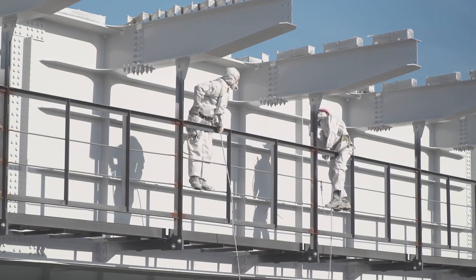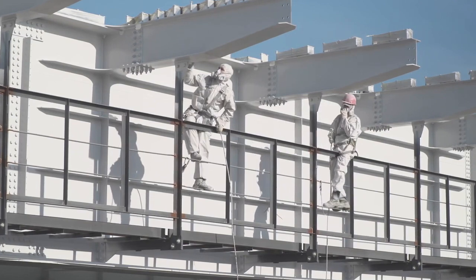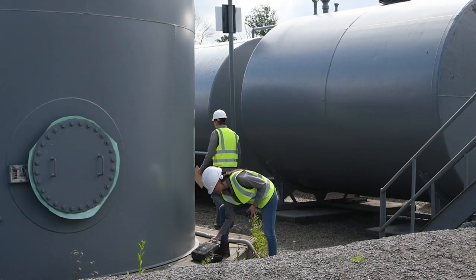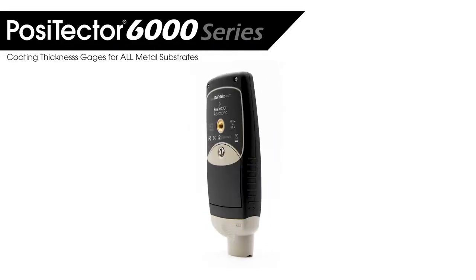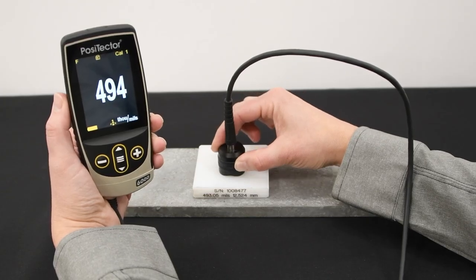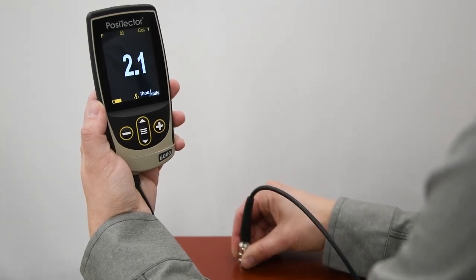Coating thickness measurement is an essential step in determining whether a coating system will perform to specifications. Color, gloss, adhesion, impact resistance, and other factors are all affected by paint or coating thickness. The PosiTector 6000 coating thickness gauge for all metal substrates is the simple, durable, and accurate way to measure coating thickness. When measuring paint thickness, it is important to never rely on a single reading.